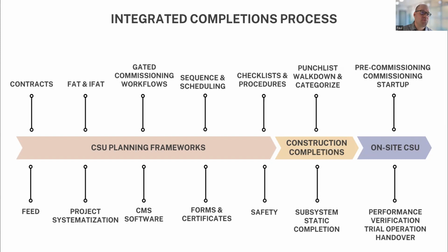Also, for equipment procurement contracts, we need to be ensuring that the right offsite details for testing some of the more complex equipment is specified in procurement contracts or specified in the contracts for the groups that are responsible for procurement. We need to make sure that our offsite testing aligns with what our expectations are for on-site testing. And if that's not defined properly in procurement contracts, then a lot of that stuff gets missed and all those issues get pushed to site, which causes lots of problems. So the first aspect there is contracts.